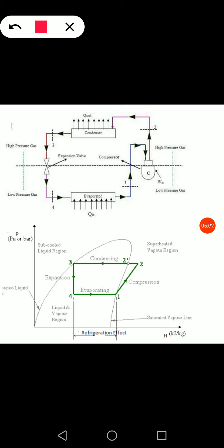As we all know, in a household refrigerator we generally use a condenser which will be cooled with the help of the surrounding air that is present in the kitchen, surrounding the condenser. Now in case of an ice plant or cold storages, we have to use water for the cooling purposes, as the load on the evaporator is much higher in comparison with the household